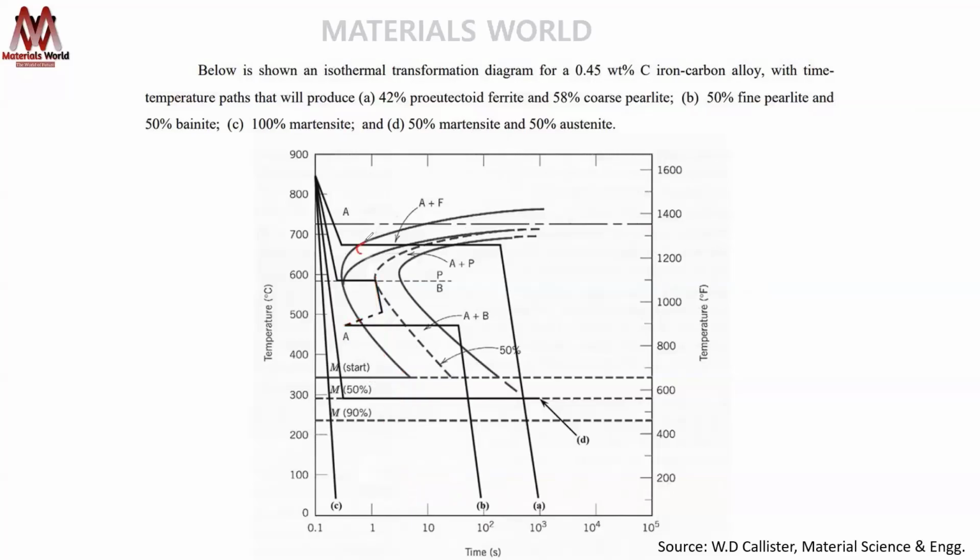For example, here you see austenite is converted into ferrite, and then all the remaining austenite is converted into finishing pearlite. All the gamma, if it has crossed the finishing line, is converted into that. Even though after that you are going down, you will not get martensite because everything is already finished.